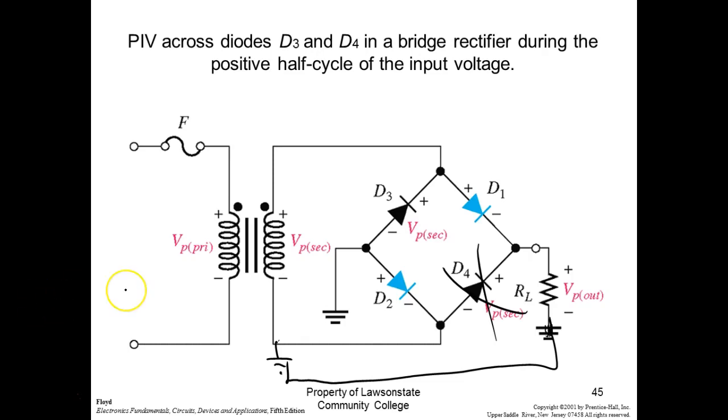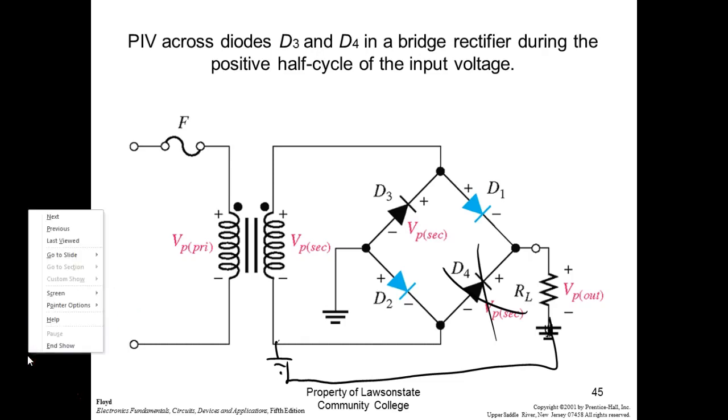Now what we're looking at to figure out the polarity is the one that, so notice here the anodes are pointing back toward the source, so that gives us a positive power supply because they're the ones on the top. So the ones on the top determine the polarity. The other ones just come back through return, right? Does that make sense? So if you look at these guys, see their anodes are pointing, these are the ones going to my reference, right? You understand? So I'm calling this common, I'm calling this the voltage.